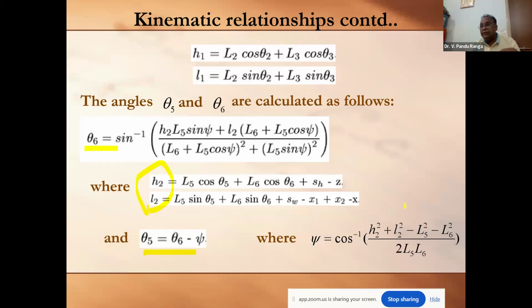As I already mentioned, theta 1, theta 7, and theta 4 are left. Theta 7 is 0 because the foot is oriented along the terrain. Coming to theta 1 and theta 4, as we would have to use the computationally expensive semi-inverse method or inverse dynamics approach, we thought of simplifying the problem and assumed no variation for the swing foot. Sometimes when we walk, we swing our foot and lift and land it at a certain angle to the ground.